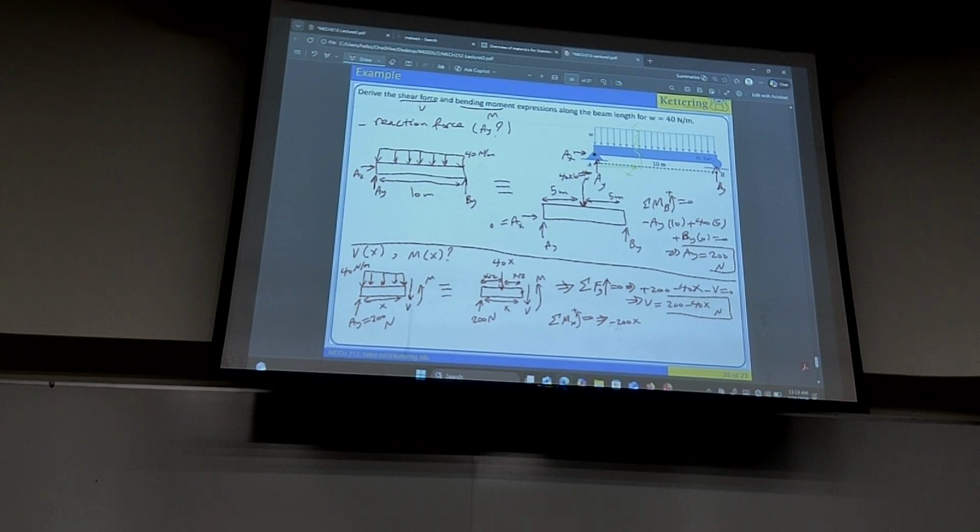Downward, it develops counterclockwise moment about x, so it is positive. This is repeated like the previous problem, I'm just having a different parameter here. So 40x is the force, the distance is x half. V does not create any moment, so V times 0.